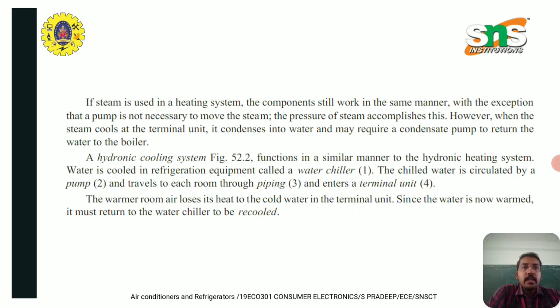If steam is used in a heating system, the components still work in the same manner, with the exception that a pump is not necessary to move the steam. The pressure of steam accomplishes this. However, when the steam cools at the terminal unit, it condenses into water and may require a condensate pump to return the water to the boiler.